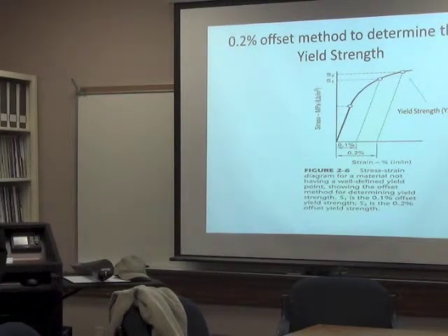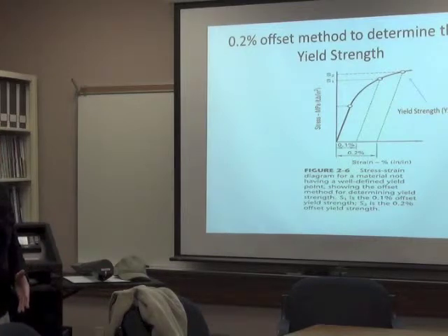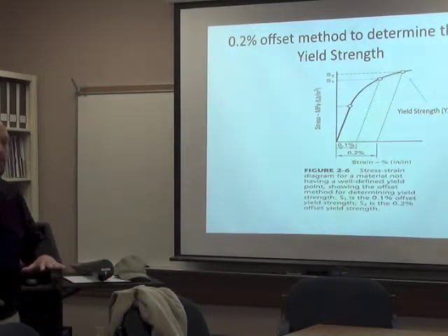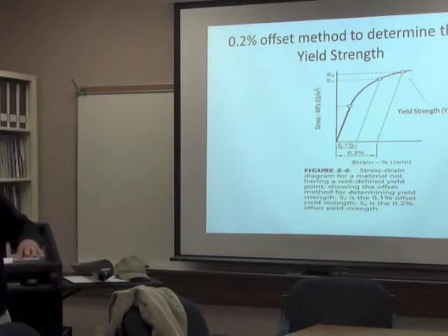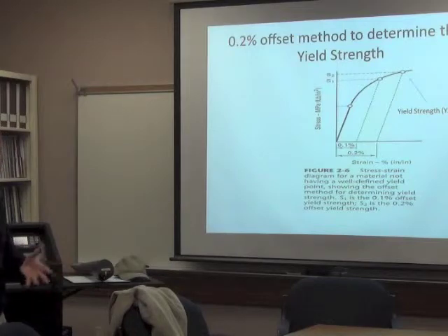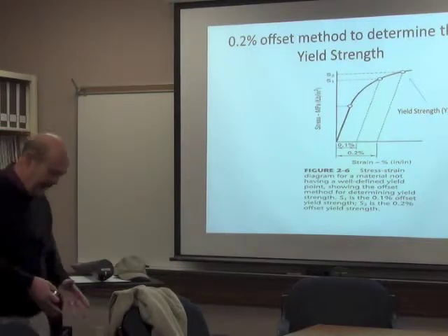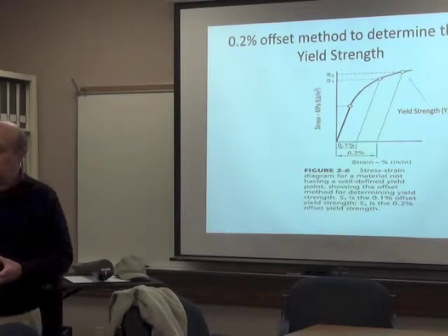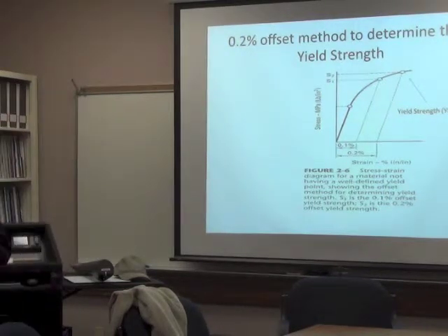The elastic or the plastic region? Elastic region, right? You want to look at the loads that you have, and you want to keep the loads below the region where you would go into permanent deformation. Or if you cannot control your loads, you want to design your components big enough in size, so you have more area to distribute the stresses, so the stresses will go down, right?